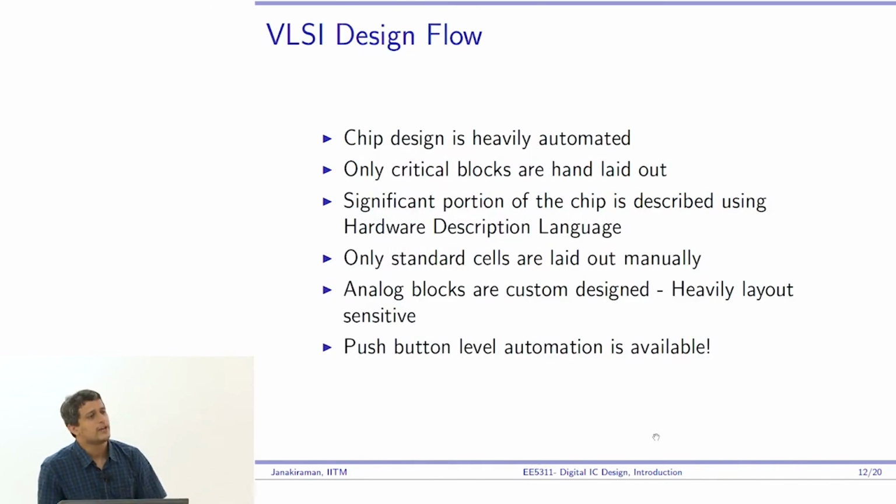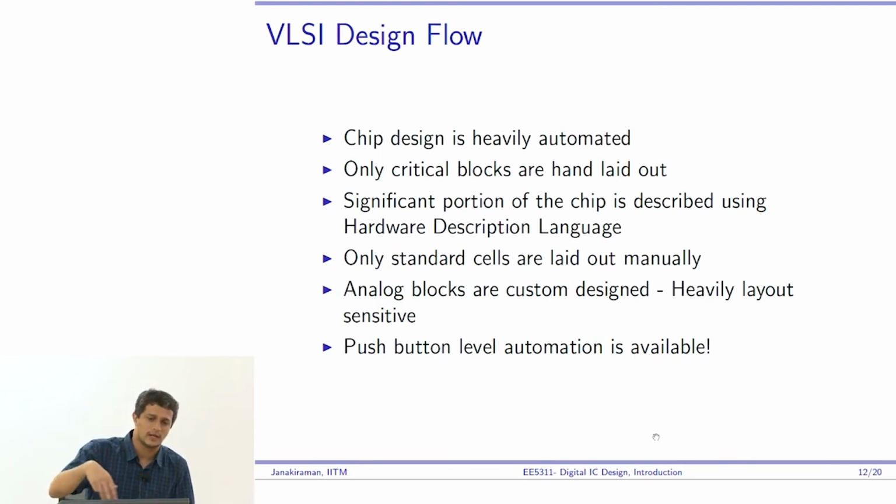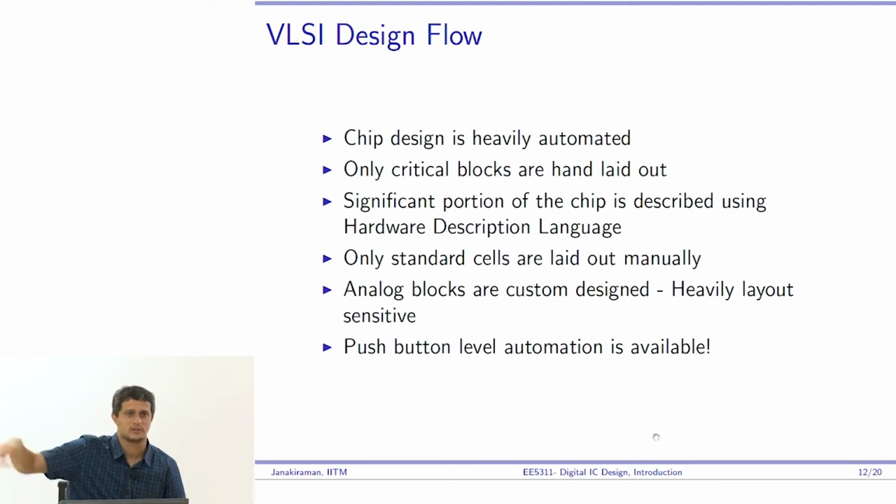It turns out that the VLSI design flow is heavily automated. A lot of this is just you write something known as Verilog code, then you can synthesize and get your layout. Layout is basically what you learn in this course. It is the eventual thing that you can ship to the foundry and say, manufacture this. It's a set of masks that you will make.